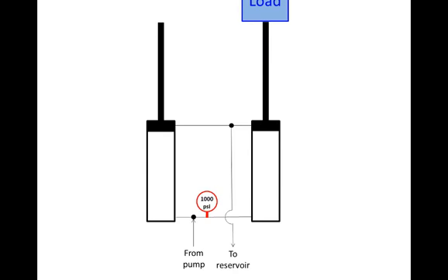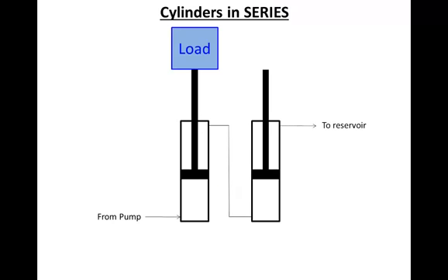So cylinders in parallel do not operate in synchronization. The one with the smaller load will extend fully before the one with the bigger load will even begin to move. Now let's talk about cylinders that are piped in series.